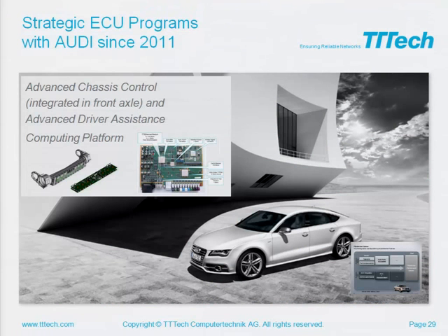I'll show you another sample that is a little bit more across industry. Here, this is the autonomous drive platform for the new Audi A8. At the core of this, there is a time-triggered Ethernet switch. And why are they using that? Because they want to reduce the memory usage of this board. If there were no time-triggered communication, if it were event-driven, here we have around 13 gigabit of data running through the board, and this would cause a lot of buffering of the different video and radar data at the board.